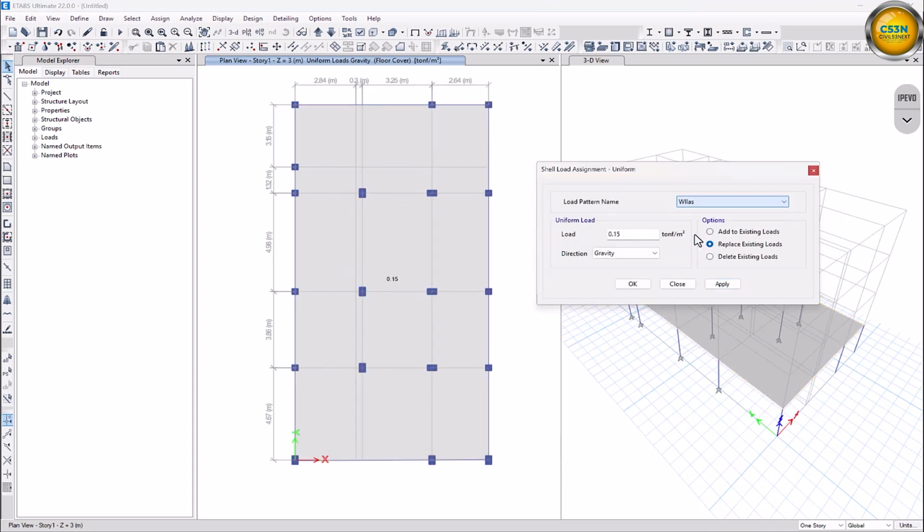Now let's add our walls. In walls, there are two ways to add the wall loads. For now, we will just add it on the slab. This is called non-exact method. There are exact and non-exact. Just let it be 0.35 approximately and click on apply. Previous selection, apply, and then click on OK.